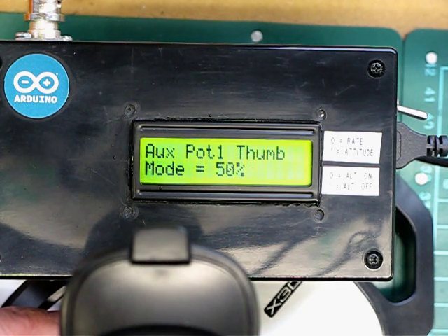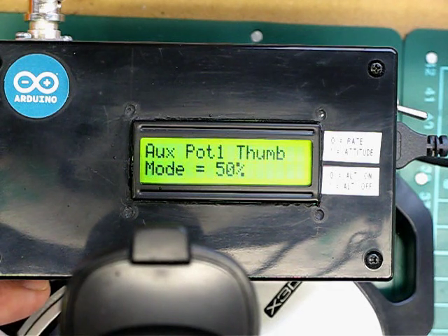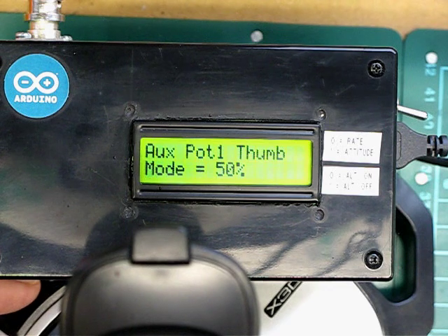So whenever you hit the thumb button on the joystick, the PPM will output at 50% and your camera will point straight ahead, and when you release the button again it'll go back to the value it was previously set at. So that's for the thumb button.